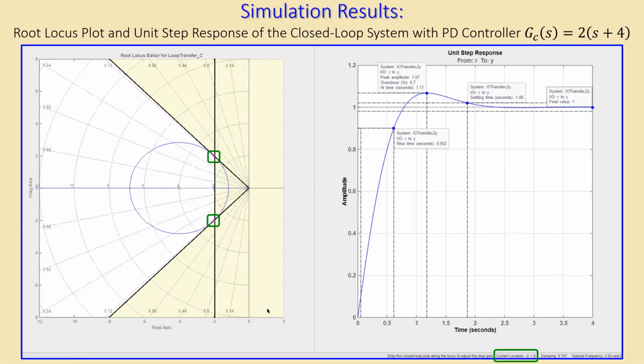It is exactly correct. You can also see that it is at the edge of the intersection of the vertical line and also the damping ratio. So I expect that this might be the best solution, maybe not, but maybe at the edge of the solution. Let's look at the step response also. And the damping ratio is again also shown here. So you can also circle that in red. You can see 0.707, which is exactly what we had calculated.